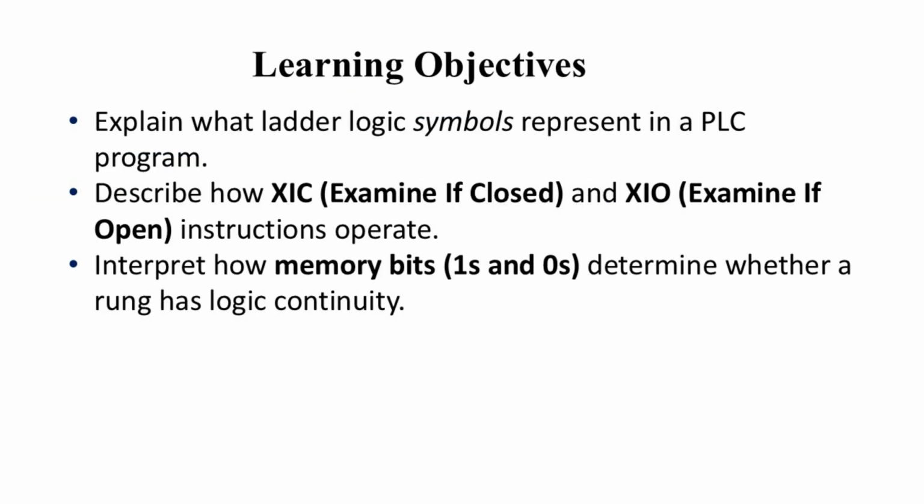During today's lecture, we will explain what ladder logic symbols represent in a PLC program, and describe how XIC, examine if closed, and XIO, examine if open, instructions operate. And finally, we will interpret how memory bits, ones and zeros, determine whether a rung has logic continuity.